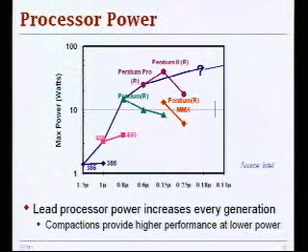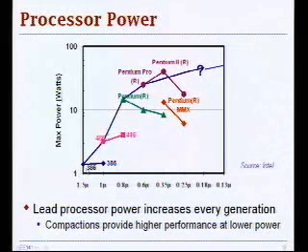So with increasing frequency and the number of components on a die, what happens with the processor power? It increases as well. And as we discussed last time, it increased rapidly up to 0.8 micron technology, where we had constant voltage scaling. And then, due to power reasons, people decided to do constant electric field scaling, scaling down the supply voltages along the way as well. So it kind of leveled off.